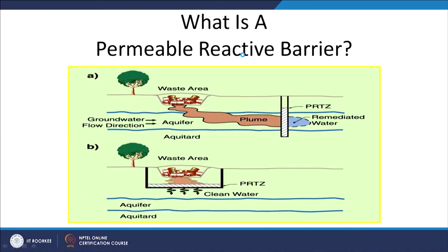So again, to help you visualize, let's say here we have the side view. You have the contaminated waste, think of this as a landfill, and let's say the liner or the leachate collection system failed, and now you have the leachate coming through, permeating through and reaching the groundwater, and then being transported over a considerable extent.